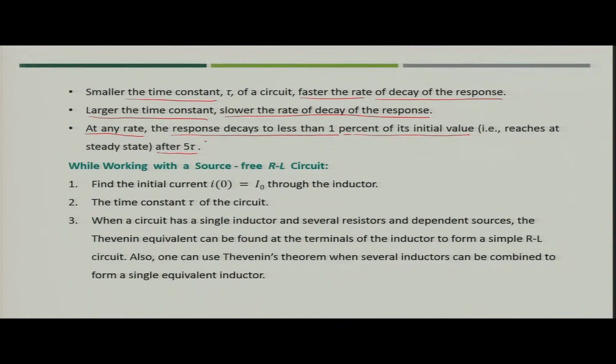So, here in case of RL circuit, the value of current flowing through the inductor will reach less than 1% of its original value after 5 time constants.